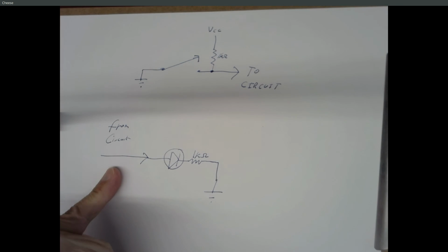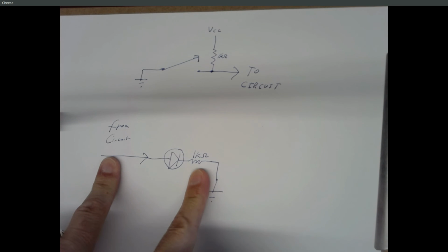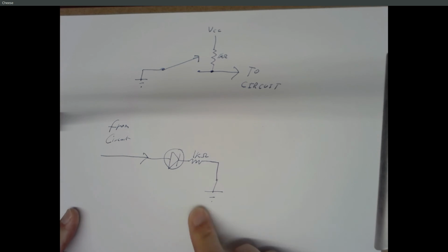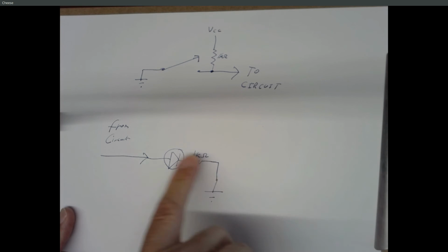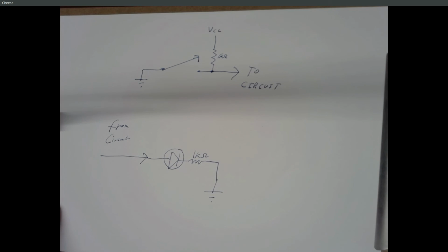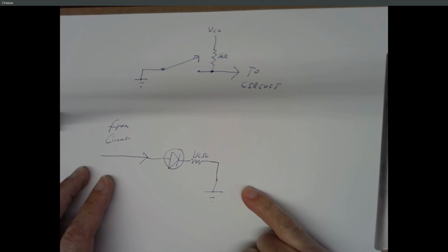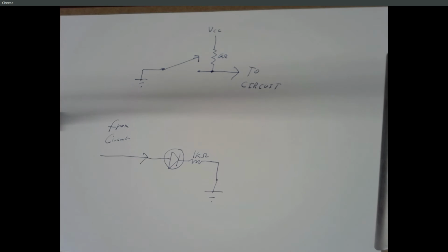And even if this is 5 volts coming straight out of Hoover Dam, guaranteed we'll never get more than 5 milliamps flowing through our LED. That's what the resistor does. So why are we putting the resistor after? You can put it after or before. Okay. Good question, but remember, current is supposed to be the same in a series circuit. So it shouldn't make any difference. You can do it wherever you like, as long as it's somewhere in that path.